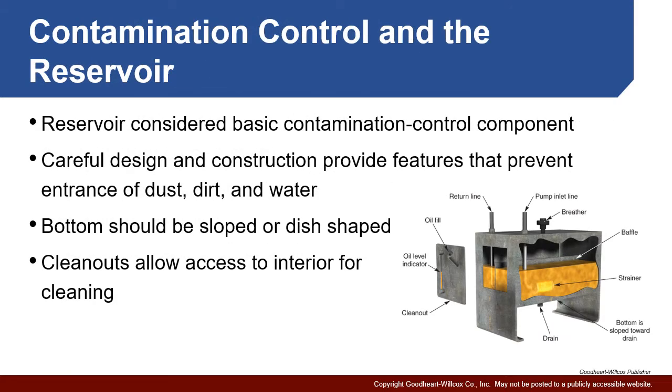While you may not think of this initially, your reservoir is actually very effective in controlling contamination in your system. The whole idea behind your reservoir is to store fluid, but keep in mind it's also designed to provide a place for the fluid to rest. During that, we want to make sure that any type of contamination separates out from the fluid. So most solid contamination we're hoping is going to drop to the bottom, and any type of gas contamination and trapped air, etc., is going to rise from the top.